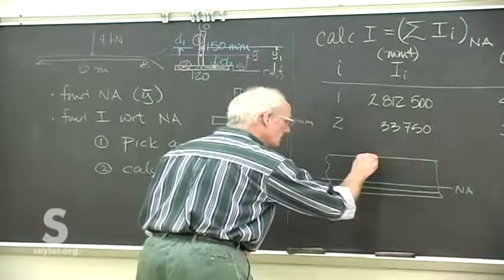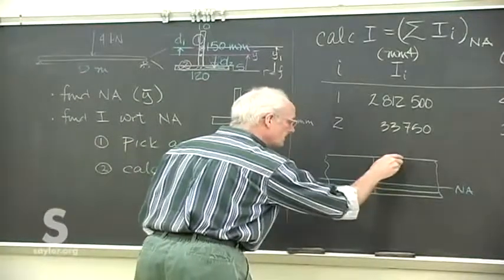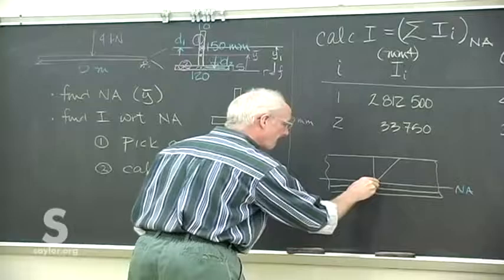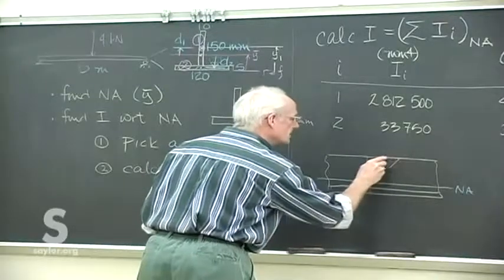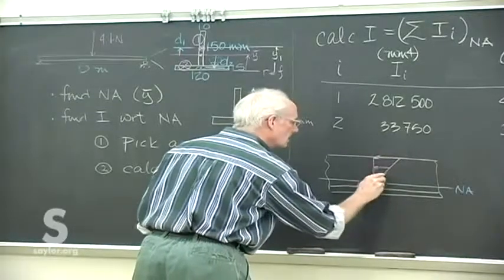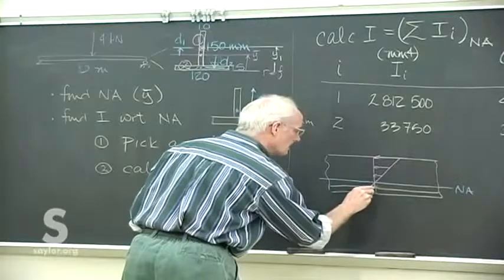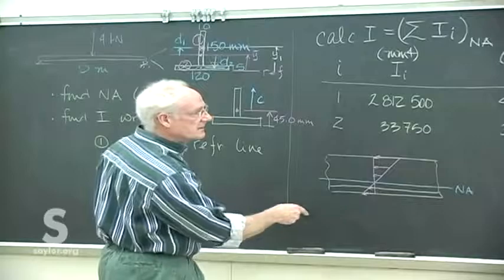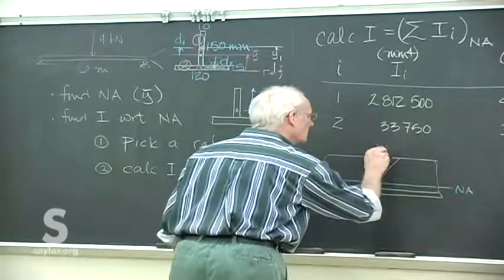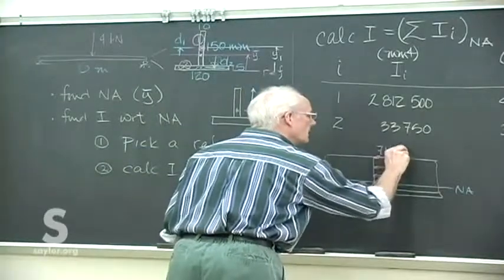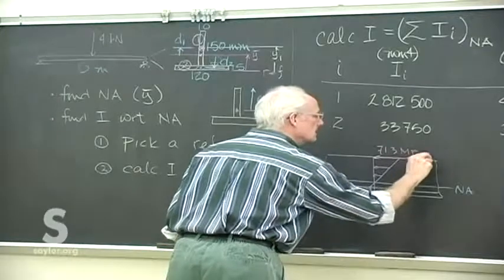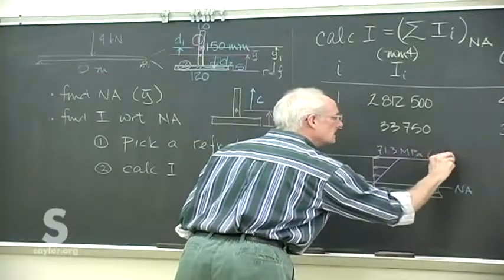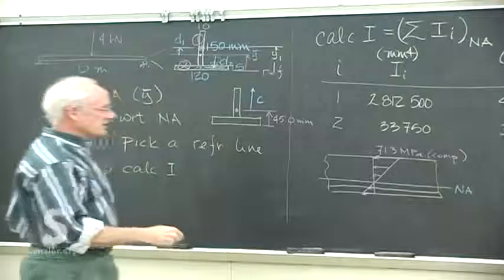And the top is in compression, the bottom in tension. And we know the maximum stress to be 71.3 megapascals compression at the top.